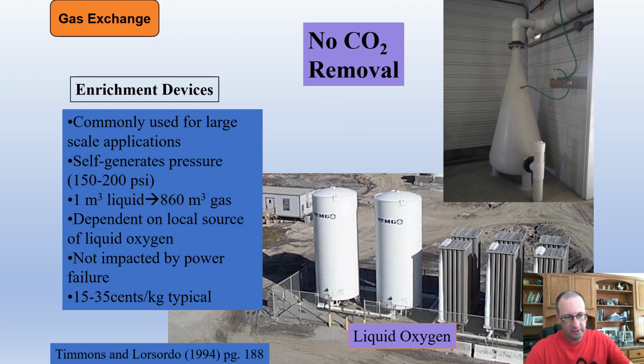And you get a little sweet spot in the middle of that where the water's flowing down like a waterfall, but the injected gas keeps rising, and so the water flow eventually pushes the gas down so far where the bubbles kind of roll around at one point in the tube, and that maximizes the amount of saturation of that particular water column with oxygen. It's a pretty interesting way to put O2 into a system, but we generally don't use it in our aquaculture operations because we don't have access to pure oxygen gas.